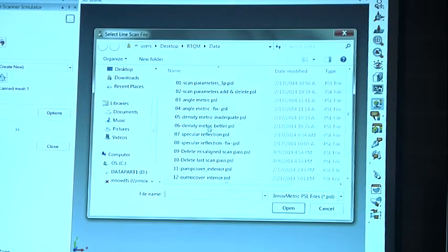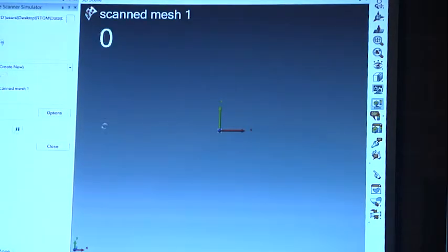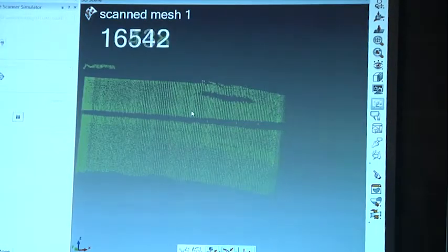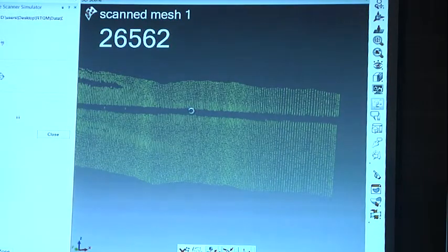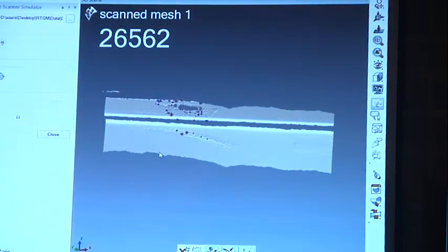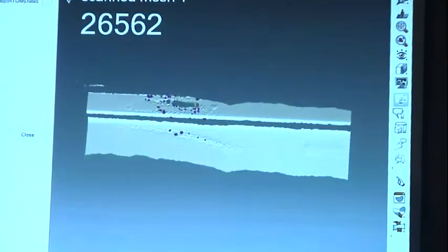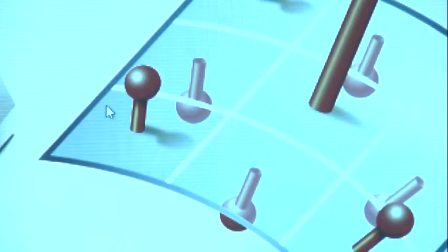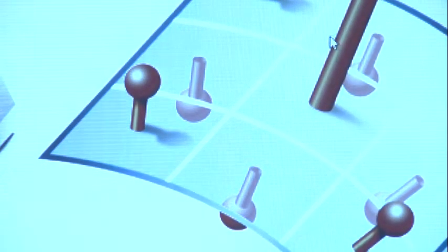If I show you that scan, the area where you have noise on it is highlighted in purple here. And the way we measure that is again by fitting some kind of a small surface there, and we evaluate the standard deviation there. If the standard deviation is bigger than a certain threshold, then we highlight this as a quality error again.